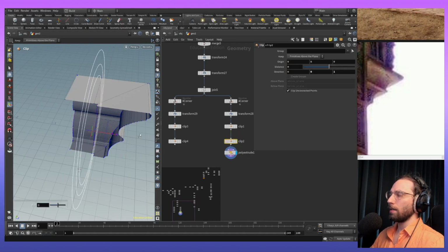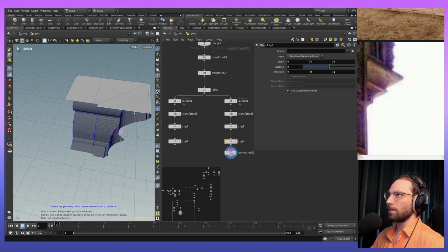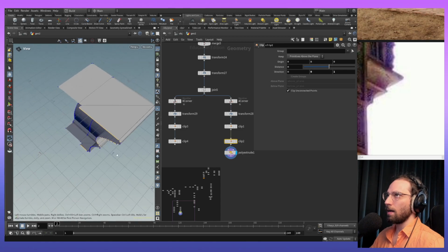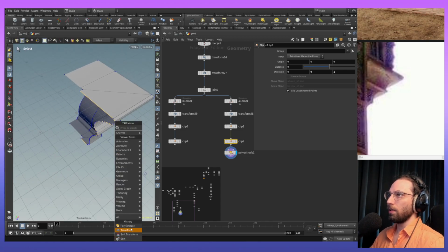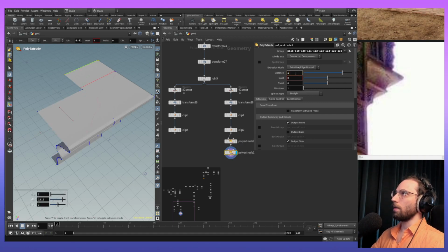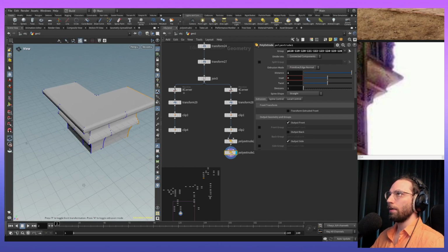We will go back right there, select our edges again that we want to extrude. Let's try the 3. 3 gives us the edges. Okay, so it's a bit different than Blender, of course, which is to be expected. Shift A, select right there, and give me the pull extrude, and we will basically put a similar value. Let's just take 1 here and 1 there. Looking good, you guys. We have 1 here, and now we need just 1 there. And now we have a corner.